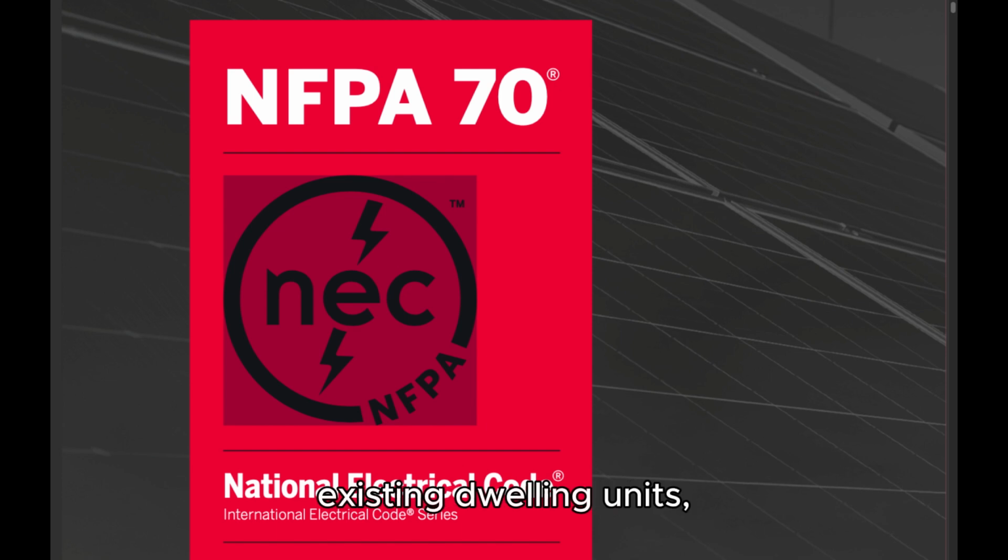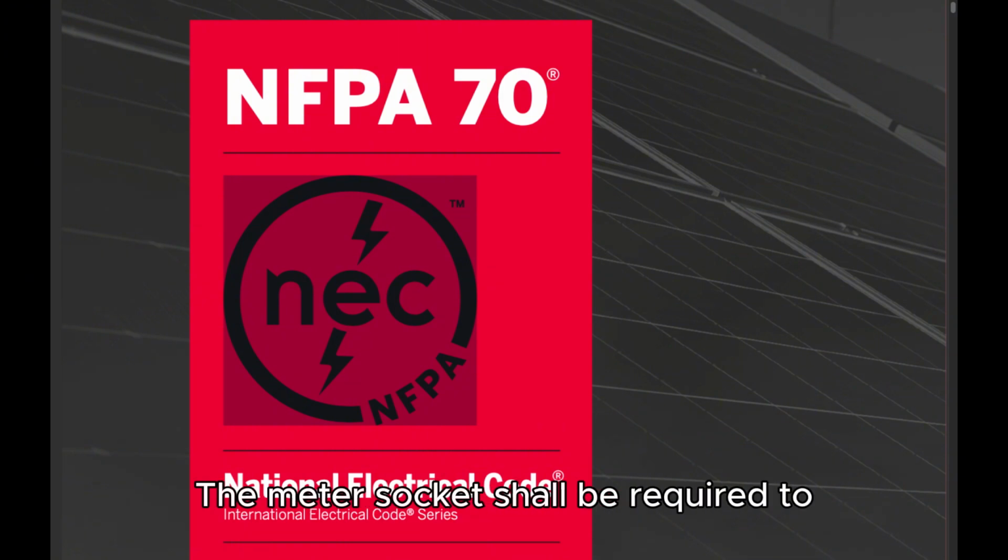Exception number 1: In existing dwelling units, service equipment or panelboards that do not exceed 200 amperes shall be permitted in spaces where the height of the working space is less than 2.0 meters (6½ feet). Exception number 2: Meters that are installed in meter sockets shall be permitted to extend beyond the other equipment. The meter socket shall be required to follow the rules of this section.